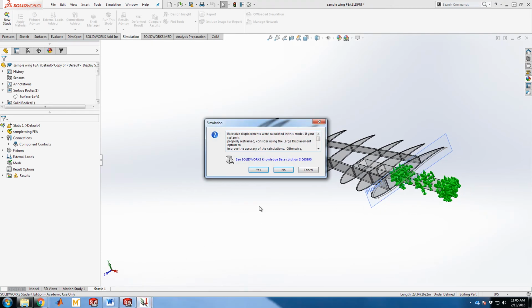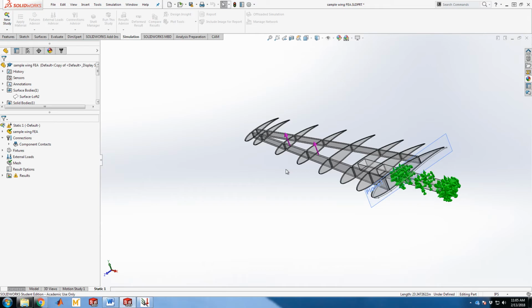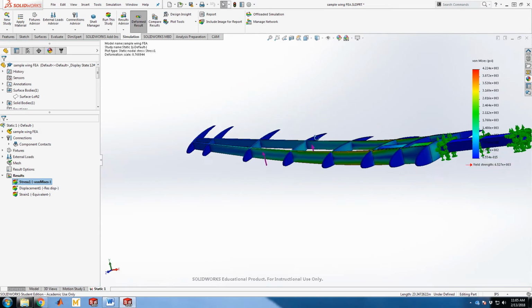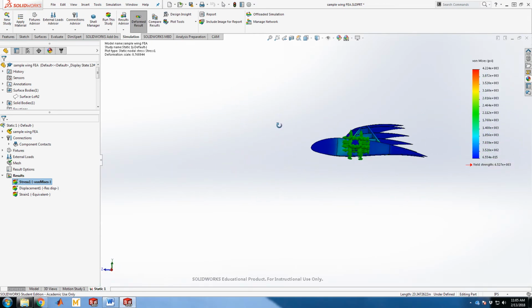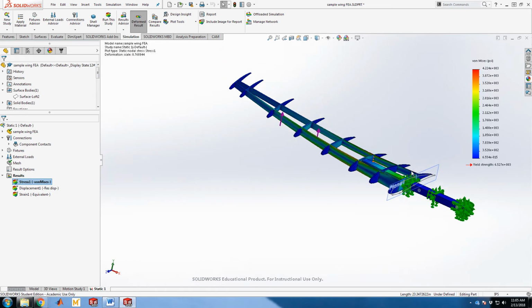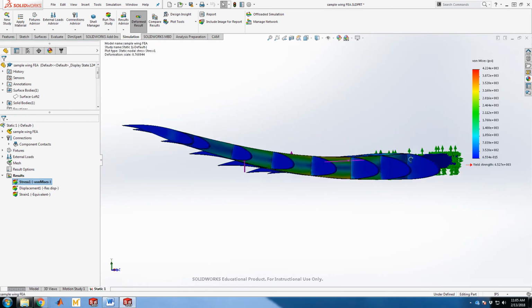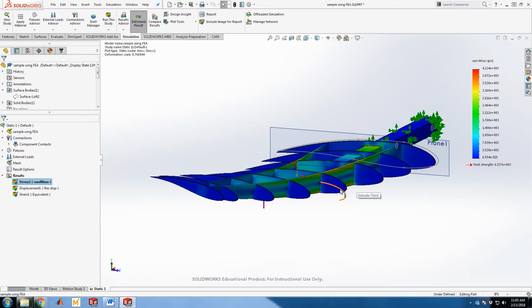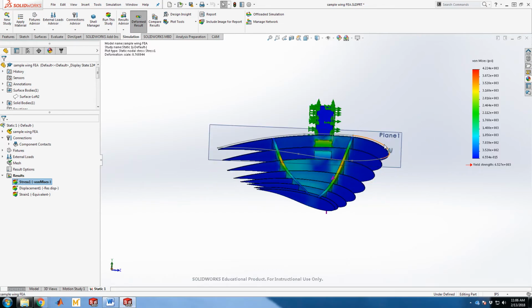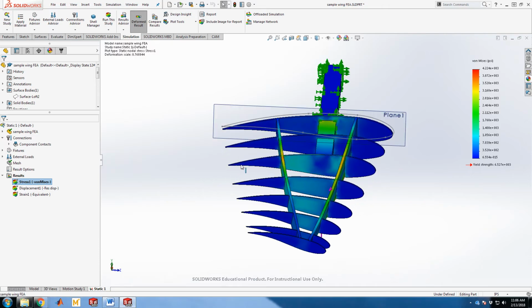Oh, come back. It's telling me there's still large displacements. Okay. But see, look at the difference that makes in total twist, total deformation. You now have a taller inertial section in the back. And this is just, again, giving you insight to where stress is occurring inside of a wing. You notice these leading edge rib sections are not stressed up at all. The trailing edge is not stressed up significantly at all.